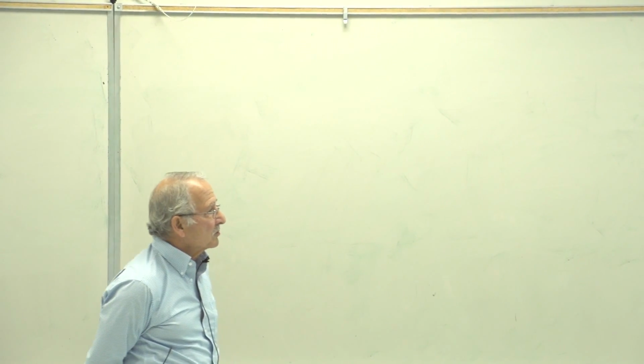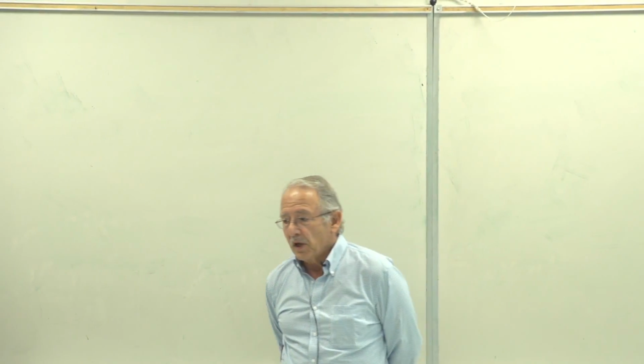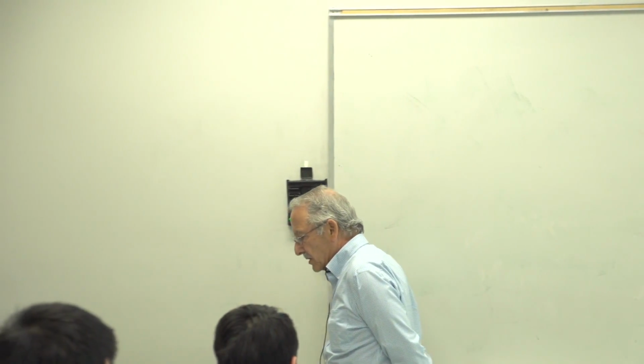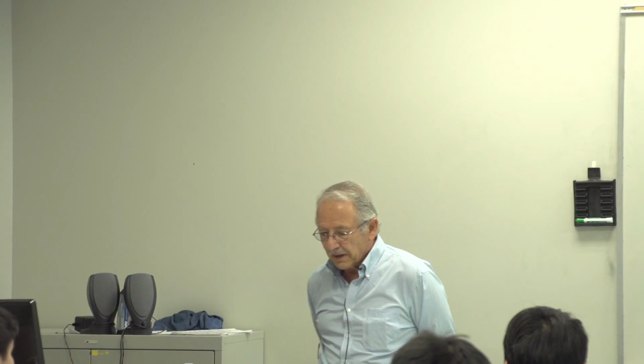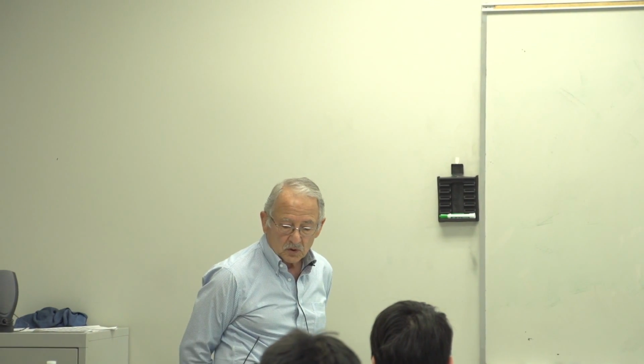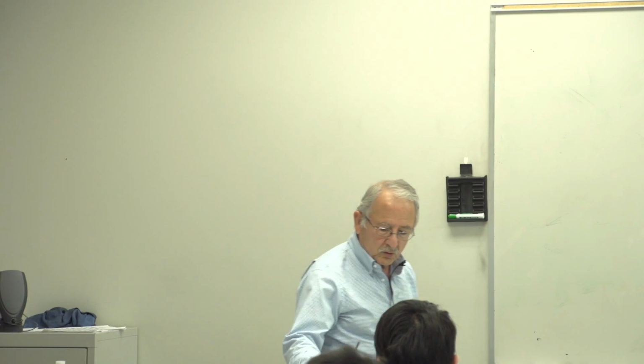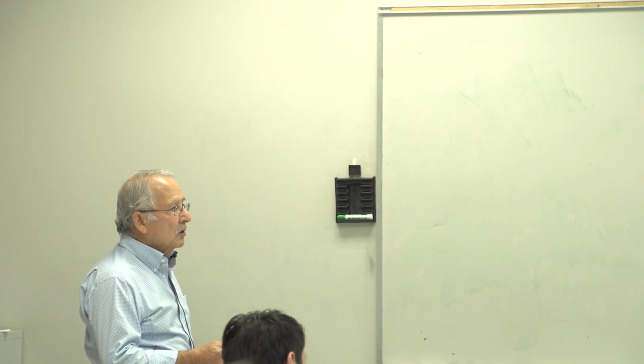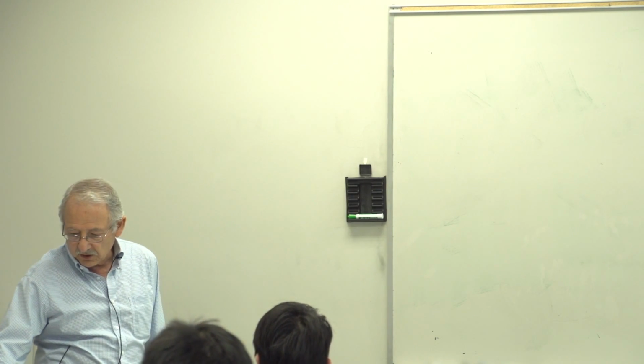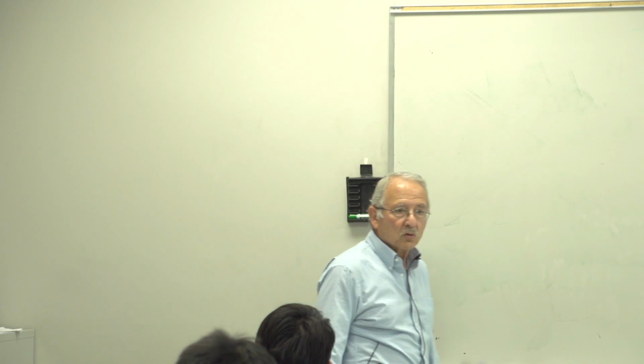Helical spring, compression springs. Because the aim is, remember, that we want to make large elastic deformations or deflections. To do that, we use Castigliano's equation. The spring wire is under two loads, a torque and a direct shear force. Therefore, the strain energy that is stored in it comes from those two sources.